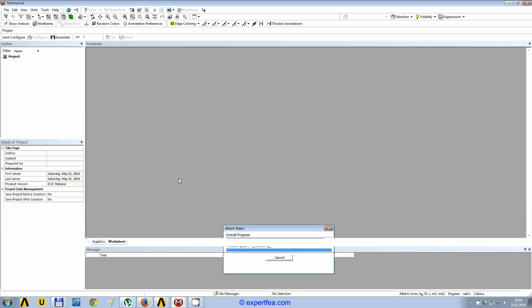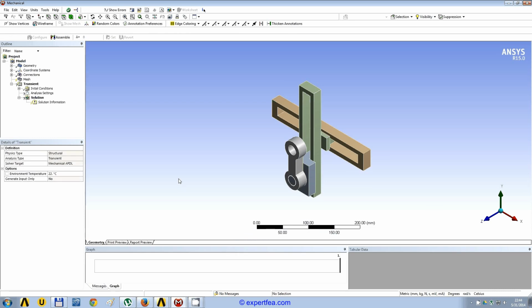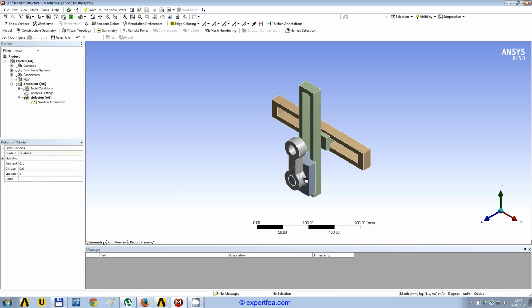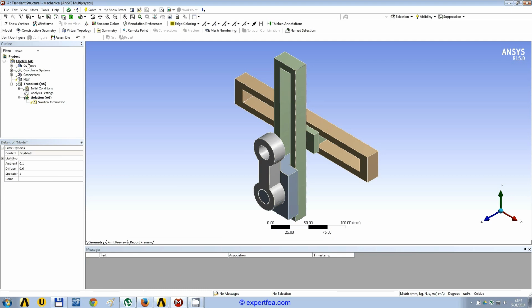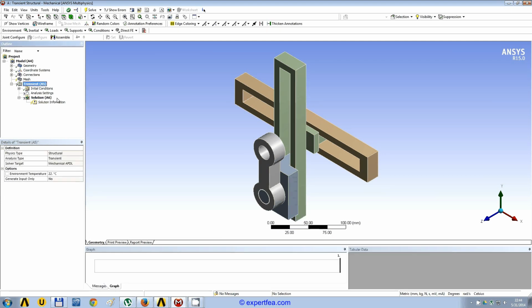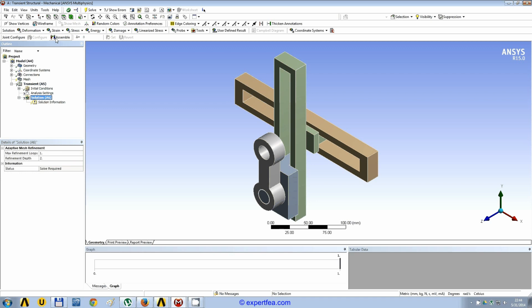I am often asked what is the difference between static structural and transient structural. The main difference is that in this kind of FEA the time has sense, meaning that we can trust and find out velocity and acceleration as output. This is not the case in the static structural FEA, where time is only a division, let's say, of the boundary condition. It's only useful to define the time steps.